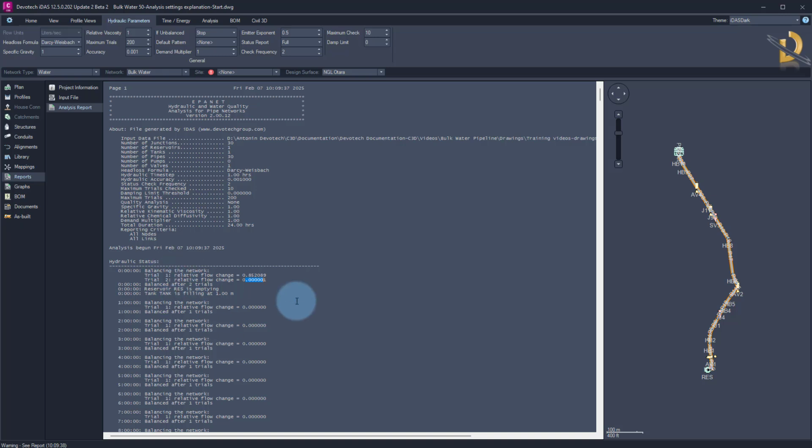And then I would need to find out what the problem is. In some cases, the network doesn't converge to a solution within 200 trials with a defined accuracy. In those cases, I need to raise or decrease the accuracy a bit, but be careful with that. What I do is check these numbers, and those numbers generally are lower and lower and lower, and then they don't go below a specific level. So my accuracy must be a little bit above. But again, if the accuracy is too bad, then you need to check whether you modeled your network correctly.